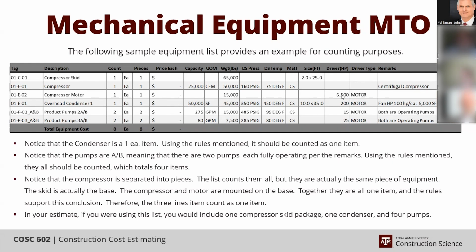The what now? The PD pumps. Yeah, positive displacements. Yeah, they're more. Reciprocating will be more. And you've got diaphragm pumps, you have gear pumps, you have screw pumps. And they all vary in price. Now the labor doesn't vary as much, because in each case you're picking up a skid that's primarily pre-assembled. You're setting it, leveling it, filling the base full of grout, and you have to check the coupling, and you have to check the seal type.